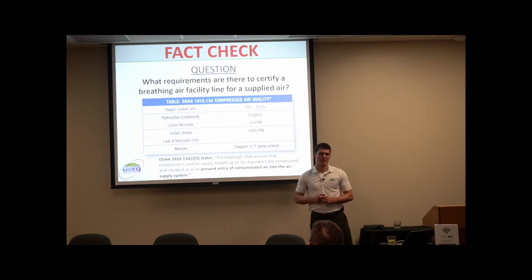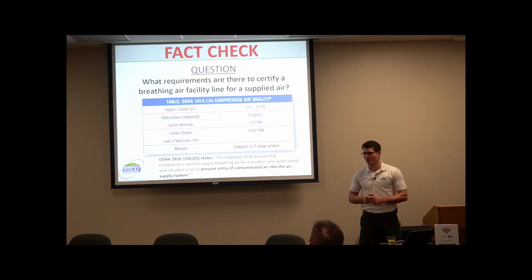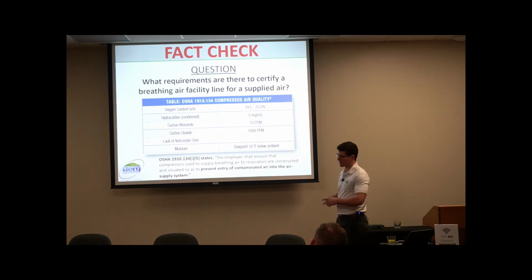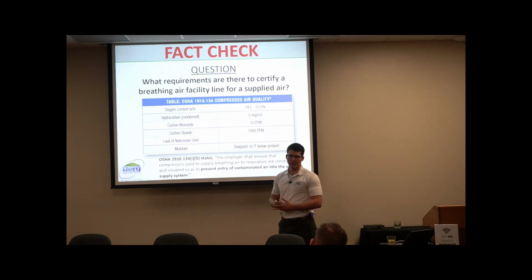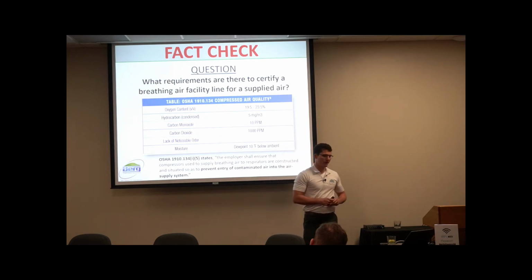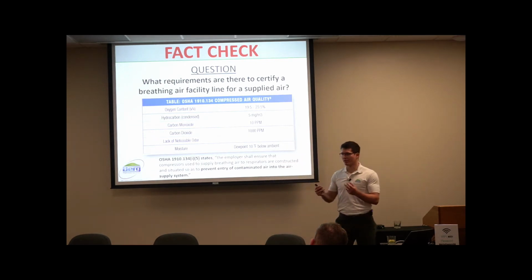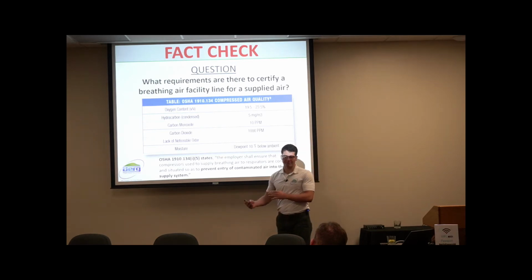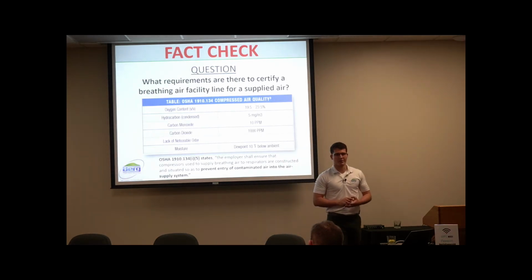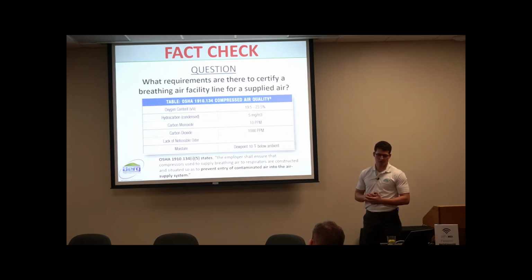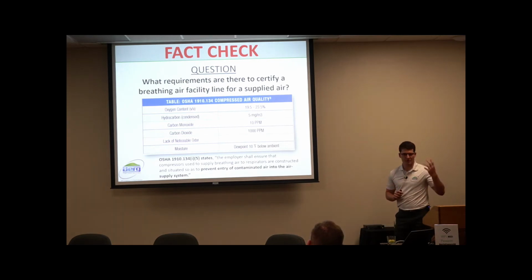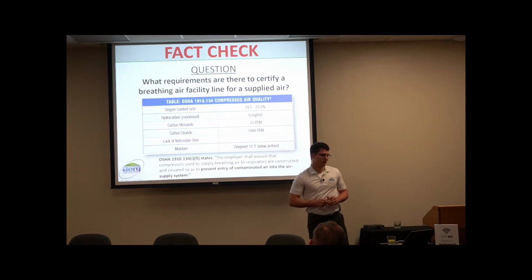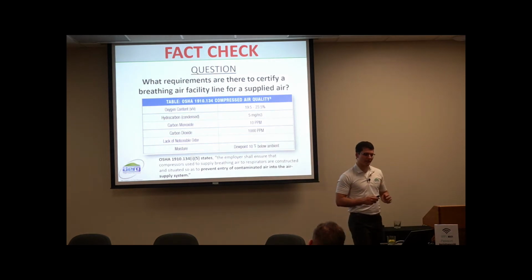So there are some very, very specific requirements if you're going to be using supplied air respirators for things like overexposures to hydrofluoric acid or hydrochloric acid, or whatever it is that is significantly corrosive, significantly damaging, with very, very low exposure limits set for a good reason. These are the kinds of things you'd want to consider if you're going to be using supplied air. A little bit different with PAPRs, because a PAPR just pulls air through that filter and filters it out innately, right?